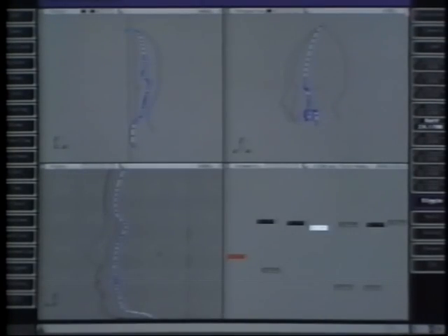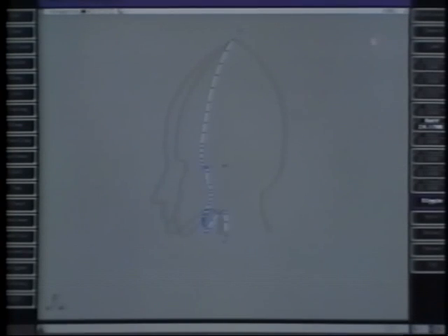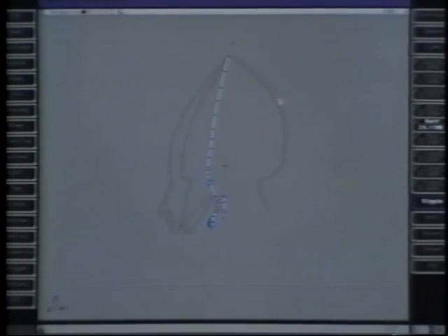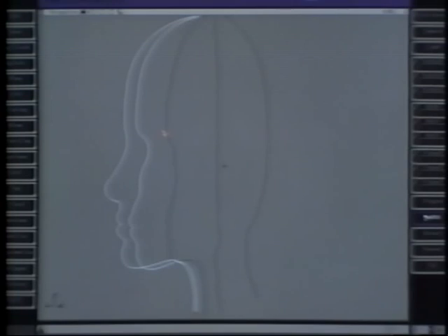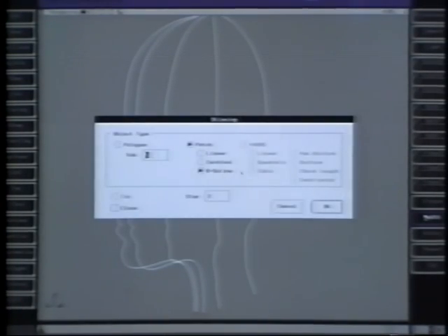We continue around making copies of the curves, rotating and modifying them. The goal at this stage isn't perfection. This is just getting us a better starting point than a primitive sphere. Just get the curves about where you want them, because we will have to add more curves and tweak the shape afterwards anyway. You can choose to draw a few more or fewer curves than this, but when you want to make a surface, just skin the curves together, and we've got a good start to our model.